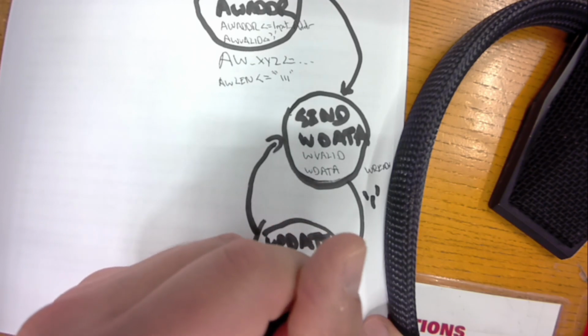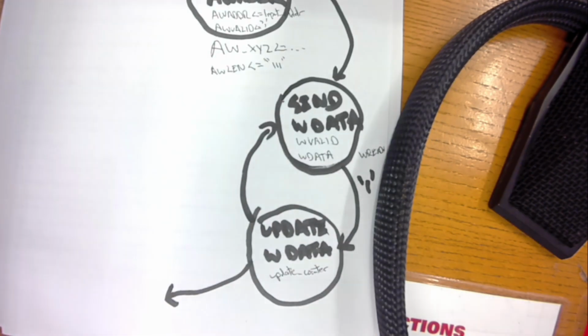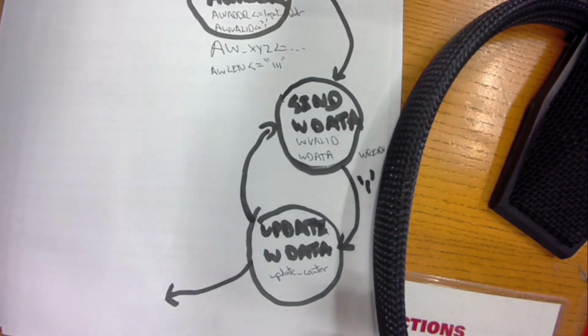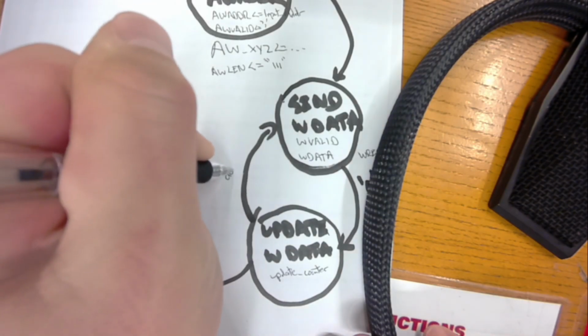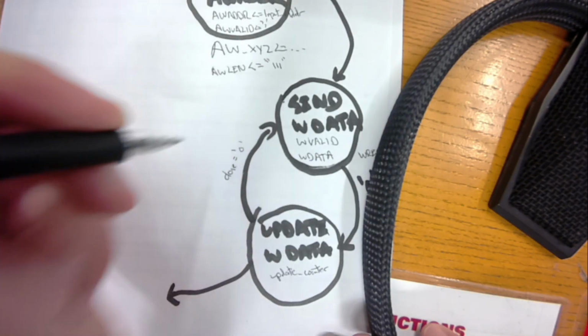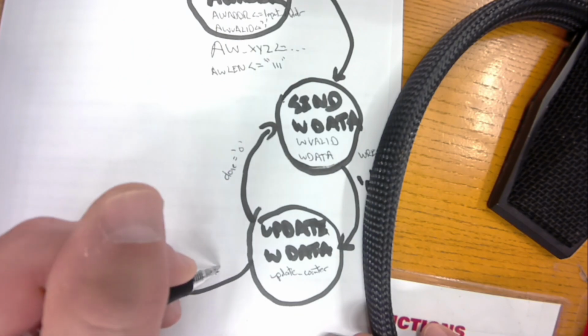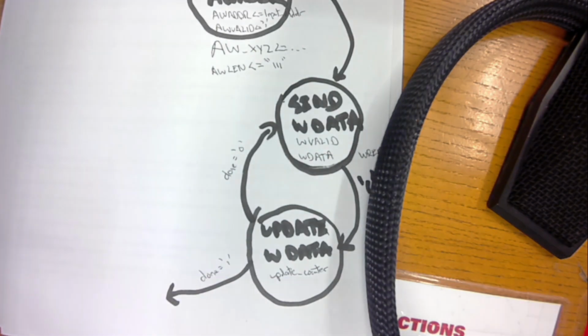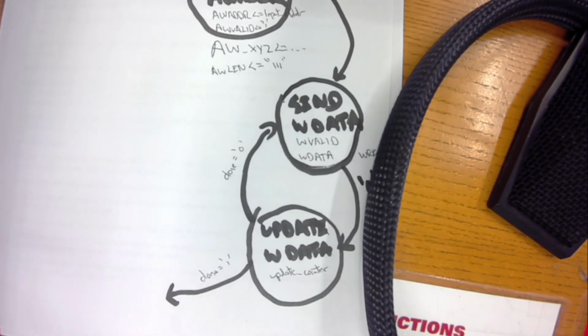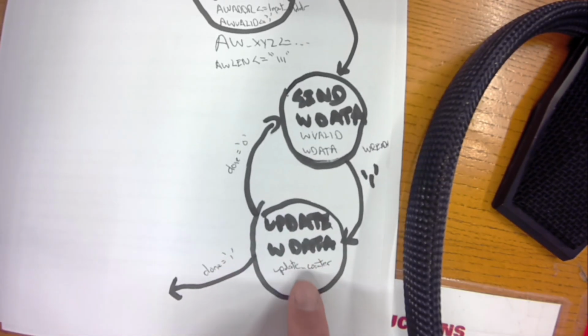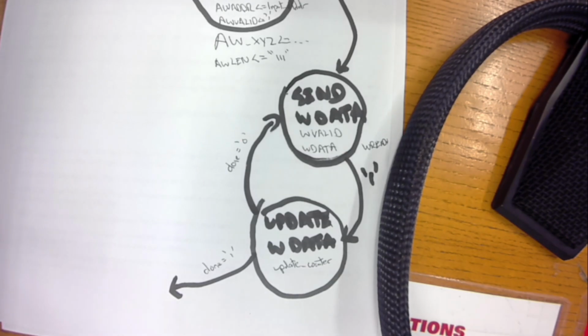So you have some other logic, which personally I would have be a completely separate process of my byte counter data value that's keeping track of how far along I am within that 8-byte burst, where I'm monitoring the done equals 0. By done, I mean done with my bursts, or done equals 1, meaning I'm done. I've sent all 8 values that are going into my burst here. That logic is also separate from this state machine, but it's also required, where this is going to be setting some signal that says, hey, increment my counter.